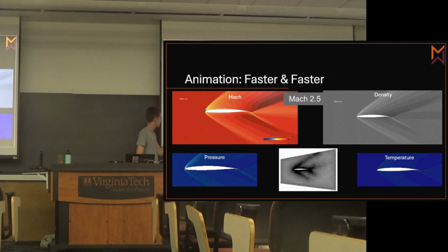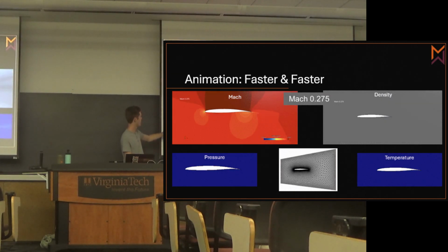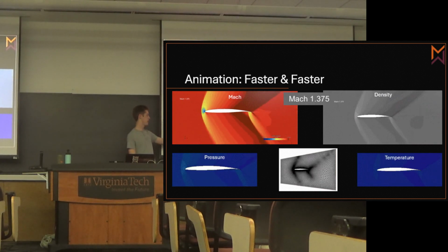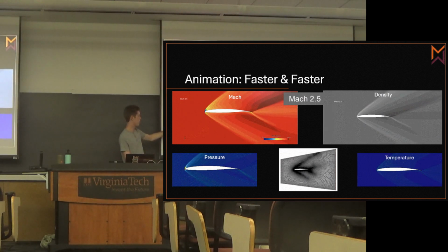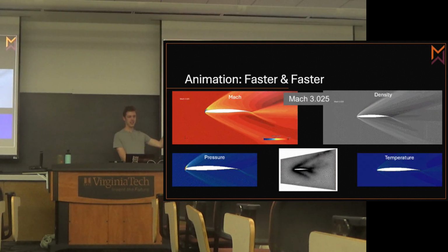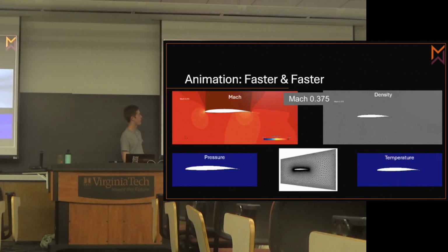Down here we have pressure. I wish I had more time to do this in more detail. We can see it's really red right here. It's because as our air comes in and decelerates, it's hitting a body, and it needs to slow all the way down, so there's a stagnation point right there. And when I take super fast air and I slow it down, I get a ton of pressure, which just translates to pressure drag right on the front of your airfoil.